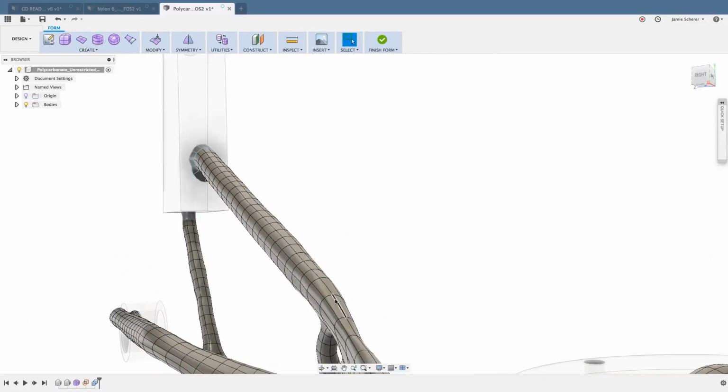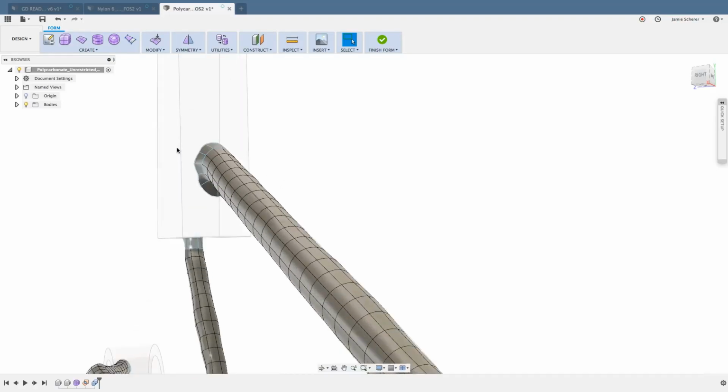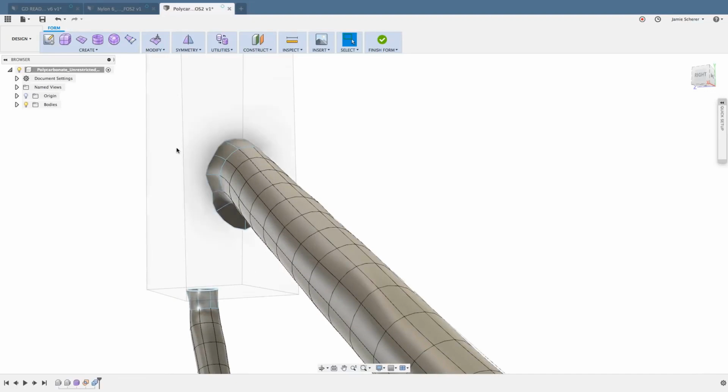This strut you can see runs and kind of terminates against our preserve regions. If you were on Aaron's generative live stream just a couple weeks ago, he talked a little bit about what this is. Now, what's happening when Fusion automatically creates the B-rep geometry, B-rep being solid geometry, in the Sculpt workspace, is that it's actually freezing those first set of edges, which is why they're colored blue.